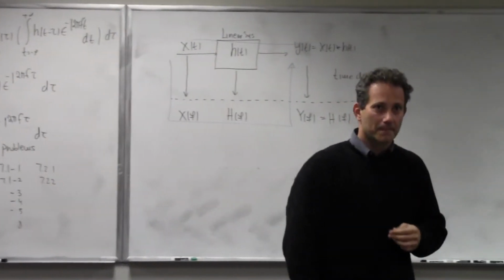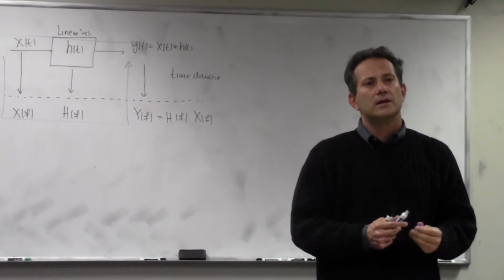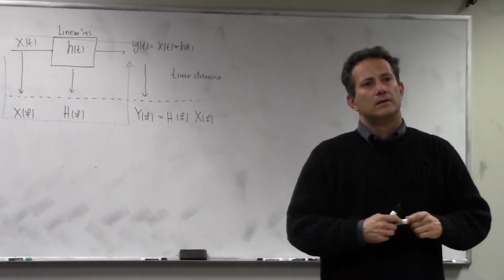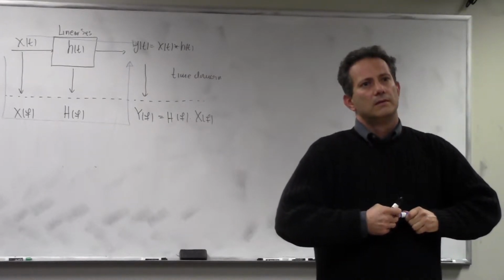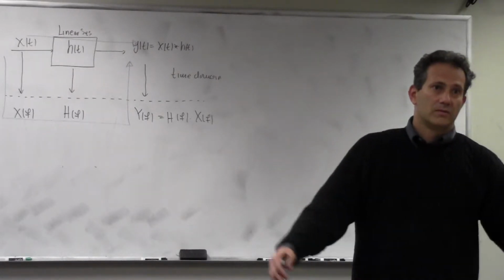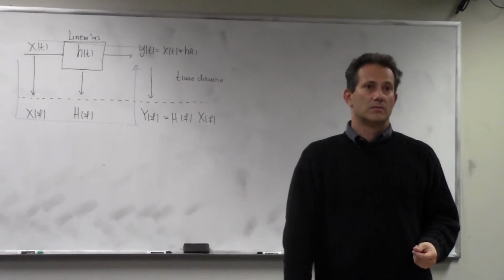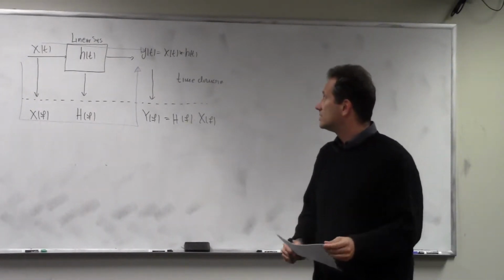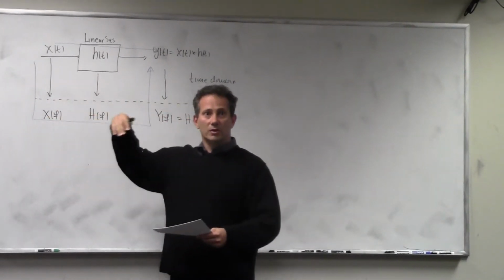Can't its own noise produce some other sinusoidal signal? Say again? The noise of the filter, its own noise, can that produce a new sinusoidal signal? Yeah, I mean, noise is made out of, especially white noise is made out of all sinusoids, right? That's why you have SNR. But a linear system on its own does not have noise, right? We model noise outside.